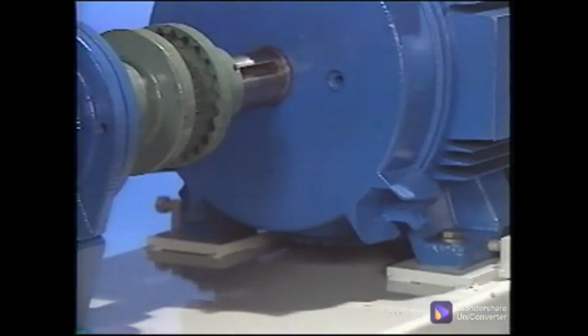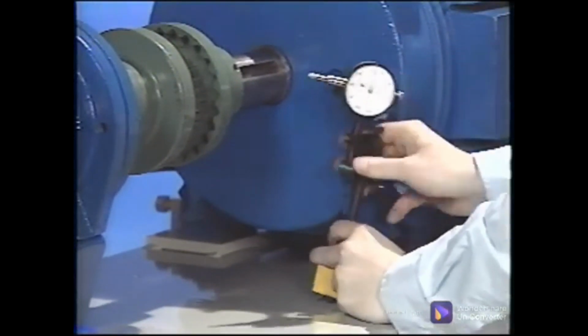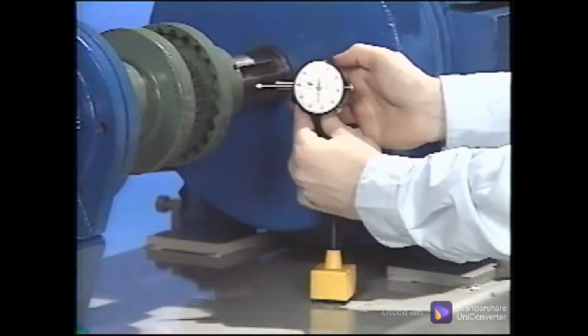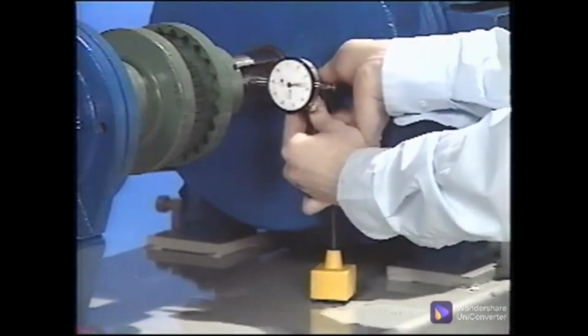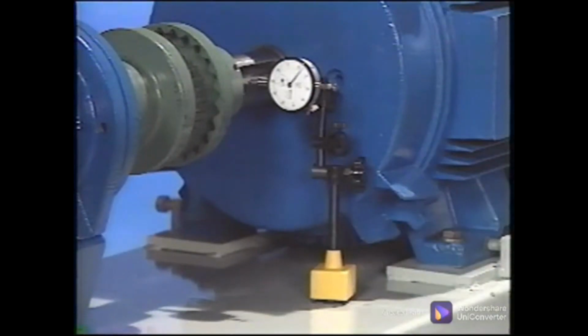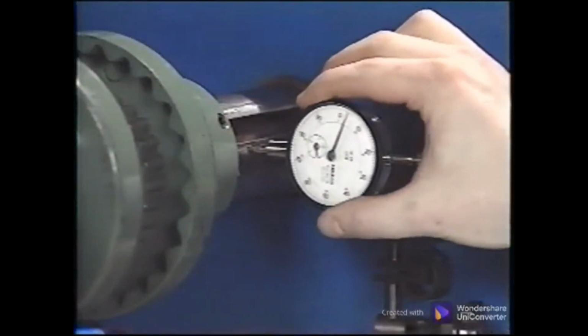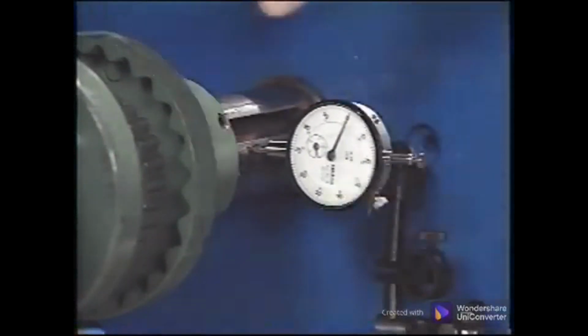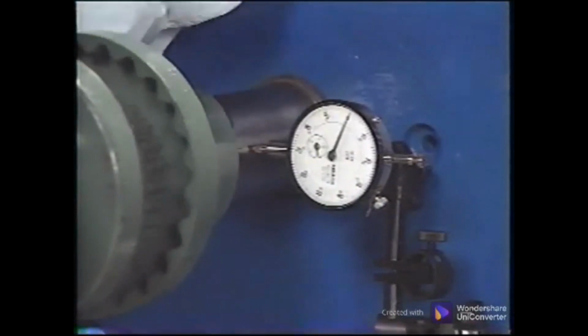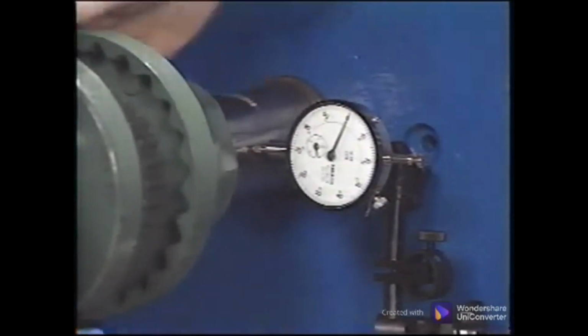Measure shaft runout for a bent shaft condition and measure the runout on the coupling. To set up for measuring the shaft and coupling runout, mount a dial indicator on the machine base or the machine component and place the plunger of the dial indicator on the shaft with it pointing to the shaft center line. Be sure the plunger is depressed about halfway to ensure good contact at all times. Zero the dial indicator and rotate the shaft, watching the dial indicator through its full swing. Repeat the procedure on each coupling hub.